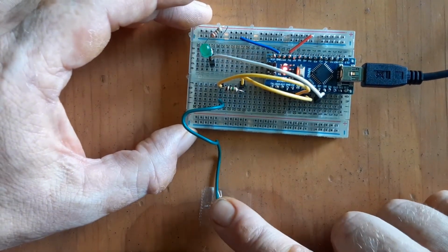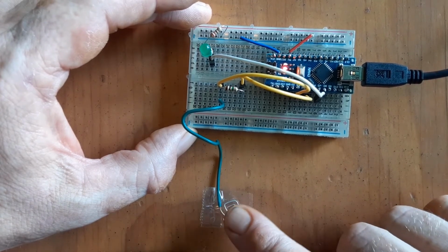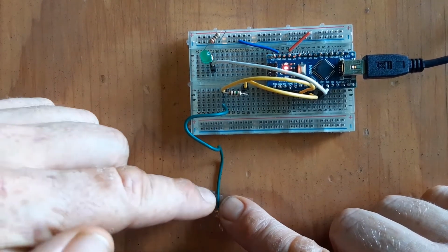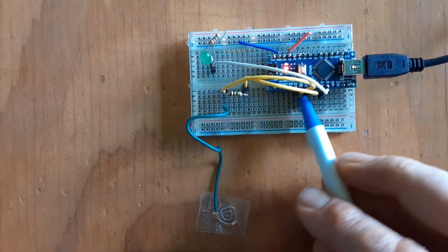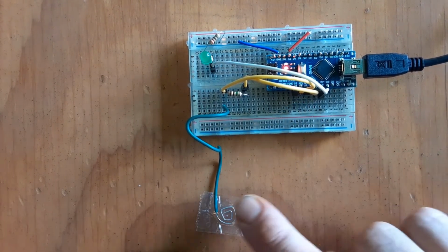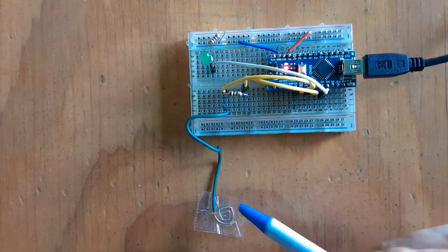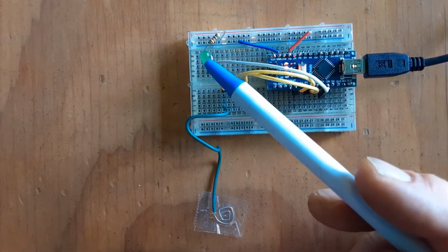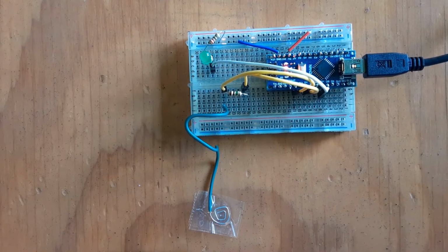And like we discussed on the board, when my finger comes in and touches the sensor, we get capacitance changing the value going through there, so the microcontroller will detect the difference of what it would be when touched and when not touched. And that's all there is to a touch sensor. And then over here is just an LED to indicate it's being touched or not being touched.